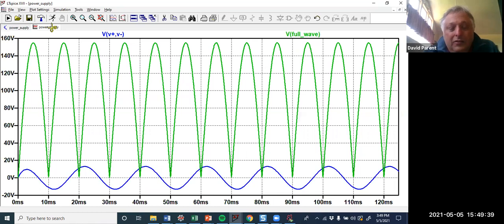All right. So now, if I were to do the Fourier expansion of this, I'd say, well, A naught is 0 because it's averaging to 0. And then I'd find the peak and call that the magnitude. And then I'd know the frequency. Here, it doesn't go negative, so the areas never cancel out, right? So there will be some DC component, and that's what we're actually going for.